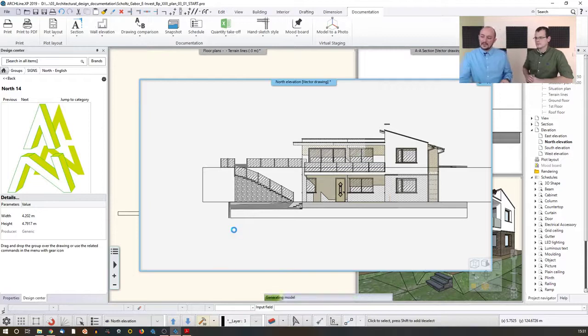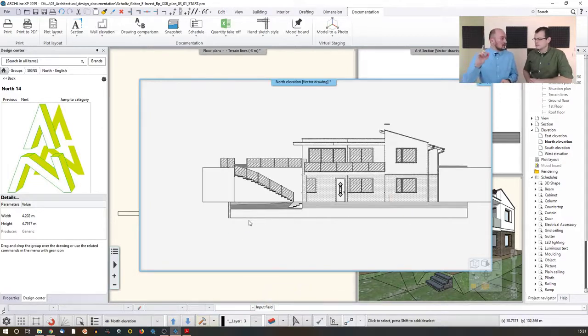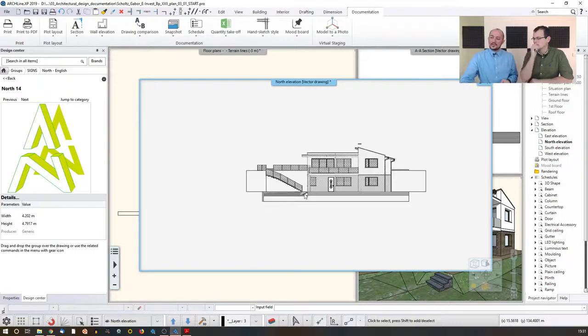So I click on this one, and this is how it happens. Now there is one more thing that I'm about to talk about when we treat the elevation. By default, the elevation is kind of an infinite plane of the building view. Sometimes I don't want to see that. For example, these here are just supporting walls. I don't want to see them fully extending how I model them. I just would like to see this model appearing on the elevation from this point to this point.